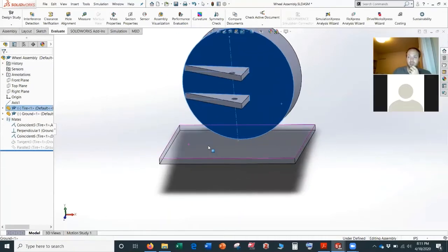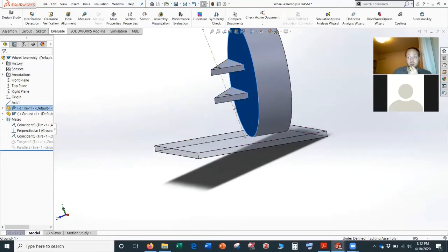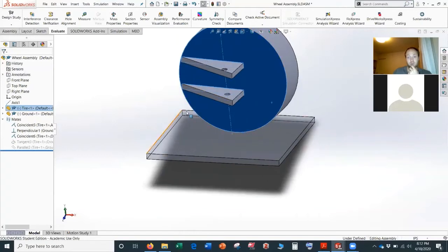But the scrub radius is known to give the driver some feel. I'm not sure it's exactly the physical mechanism behind that. Probably has, again, something to do with transferring these forces to the steering wheel and to the driver in this case. Whereas if you have your steering axes go right to the center of the tire, a lot of the forces on the tire are going to be held by the suspension members and are not going to be held by what holds the toe. So the driver is not going to get quite as much feedback and feel, which maybe isn't as important for our autocross, just because you guys are going quick in and out of turns. You're not really trying to find the very edge. And so keep that in mind. So okay, so that's kind of the kingpin inclination, ups and downs, and scrub radius and how they interact together.